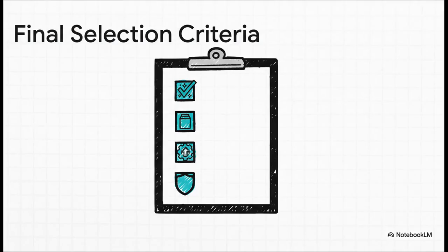Okay, armed with all this knowledge, Alex puts together a final checklist for the new machine. Number 1, air quality. Must be 100% oil-free, no exceptions. Number 2, capacity. This time it's sized for the real demand, plus a buffer for future growth. And since this new machine will be a base load unit running all the time, full load efficiency and reliability are critical to keep those operating costs down.